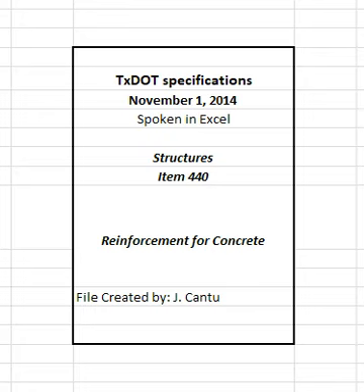Provide deformed steel bars of the types listed in Table 4 and conforming to ASTM A955, grade 60 or higher when stainless reinforcing steel is required on the plans. Table 4. Acceptable types of deformed stainless steel bar. See table in specifications. 2.11 Low carbon/chromium reinforcing steel. Provide deformed steel bars conforming to ASTM A1035, grade 100 when low carbon/chromium reinforcing steel is required on the plans.